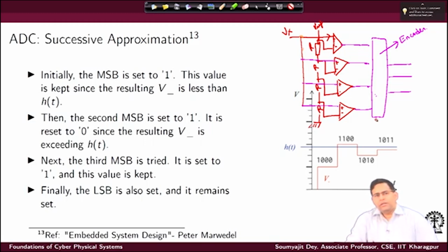What is the disadvantage? Well, it requires more hardware resources. For example, in this example you are requiring 4 comparators instead of using one single comparator in a serial manner when you generated that successive approximation signal, right? So that's one alternative here for you.